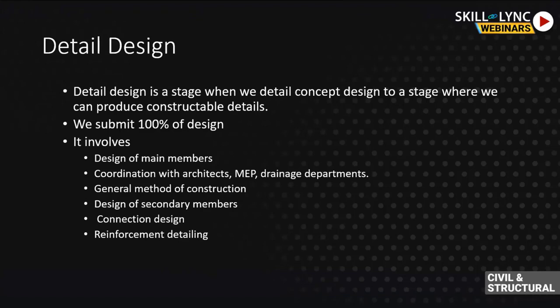So say you have a very simple lift shaft drawing, and you have four drawings for it. One is the steel drawing, another is the connection drawing, and then you have to give the foundation drawing for it, and you have the reinforcement drawing. So typically what happens is your foundation is casted by some other contractor and your steel work is done by the fabricator who develops the fabrication drawing based on your detailed design drawing. So the fabricator has to develop his fabrication drawing. He is not concerned much about the reinforcement drawings. But if you haven't segregated the drawings properly, he will have to deal with your reinforcement drawing unnecessarily.